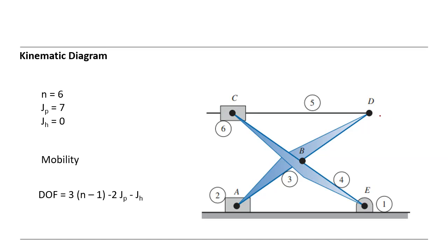So let's write the degree of freedom here. Here we have 1, and here we also have 1. This is the rotation, and the rotation here. And here we have sliding, 1. And here we also have rotation, 1. And here we have sliding 1 and rotation 1. And this is grounded.